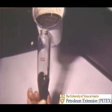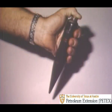Another test is a measurement of the percent by volume of sand in the mud. Sand is abrasive and causes erosion of metal and rubber parts of the rig. It is important to keep the sand content at a low level at all times. First, a sample of mud is poured into a special tube to the level where it says mud to here. Water is added to the mud and the tube shaken to mix the water and mud together.